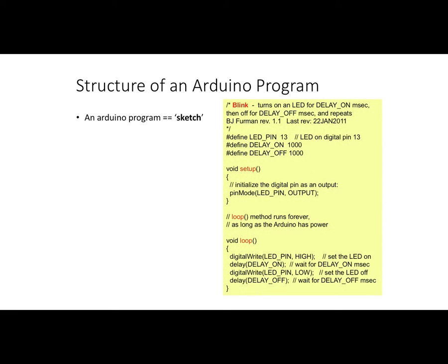So here's an overview of a sketch. I'm going to unpack and describe the pieces in a little bit more detail later, but we can see now how the pin mode is being set to output, and setup is the first thing you do when you run the program. Essentially it takes an init and calls it just once, and that's a critical thing to getting your code configured.